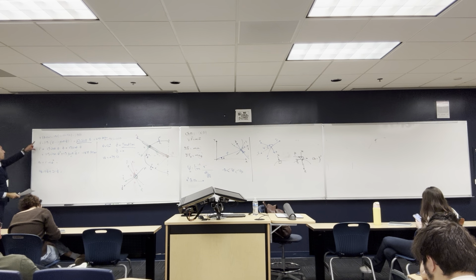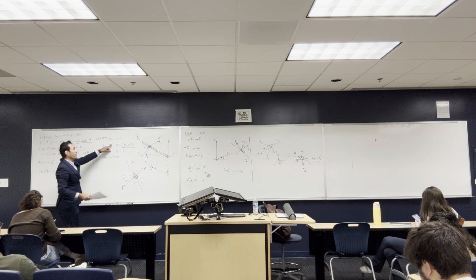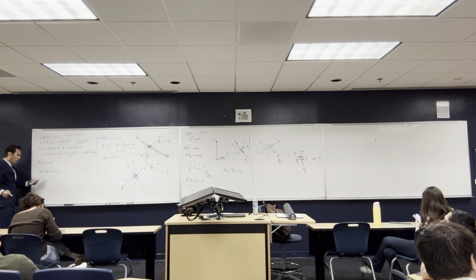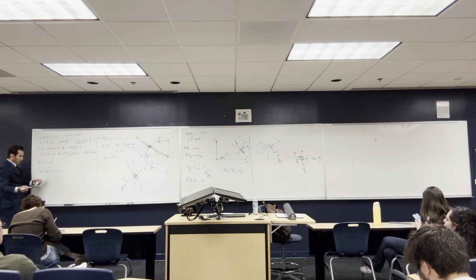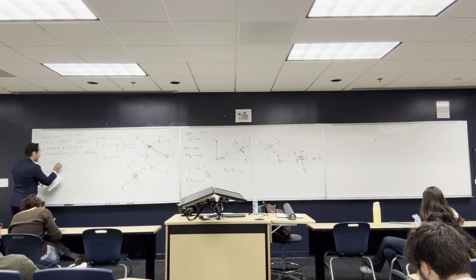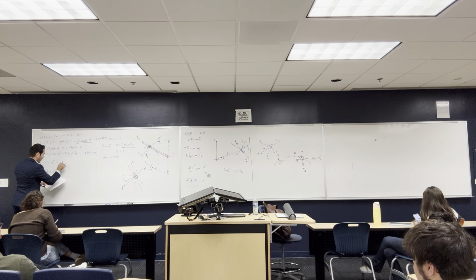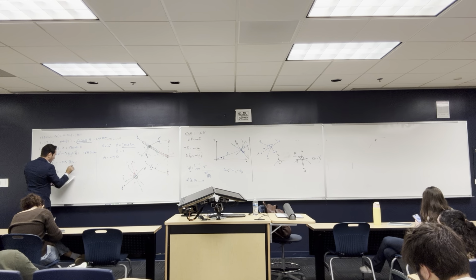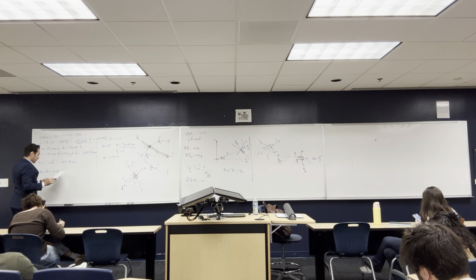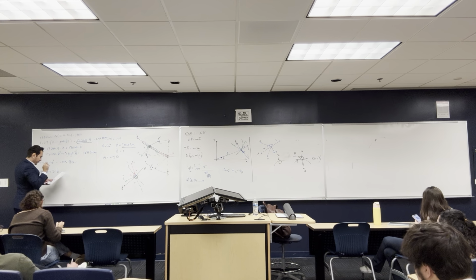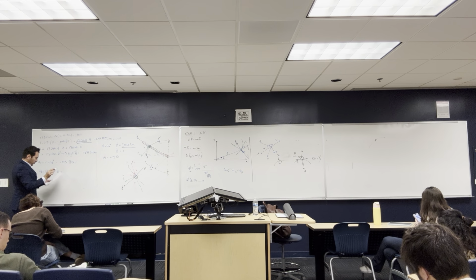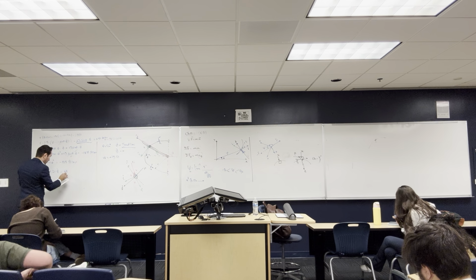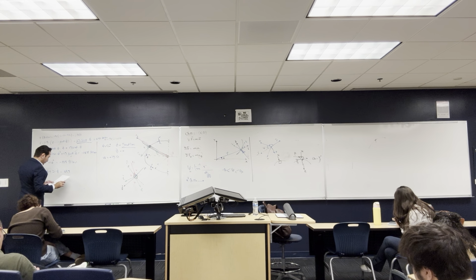So basically I have all the R dot and double dots, I have all the theta dot and double dots, so you basically substitute here, and you are going to get that A_R is equal to negative 112.5 feet per second squared, and you are going to get A_theta is 64.5.